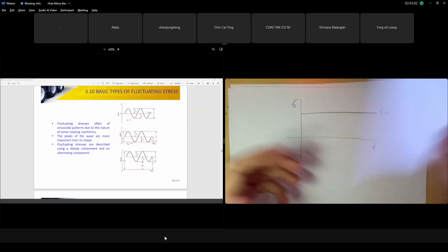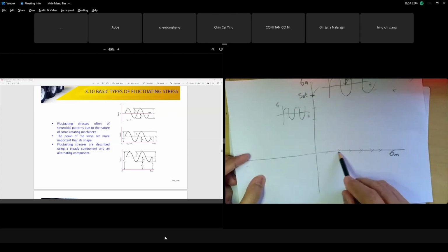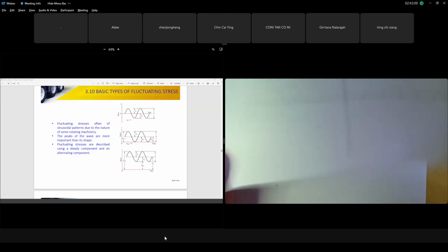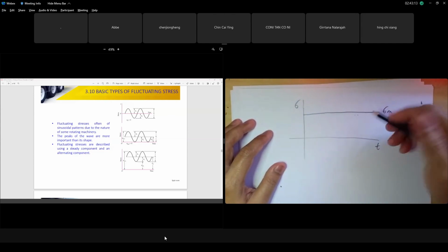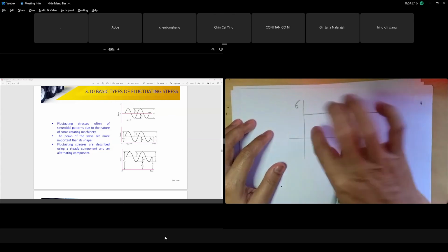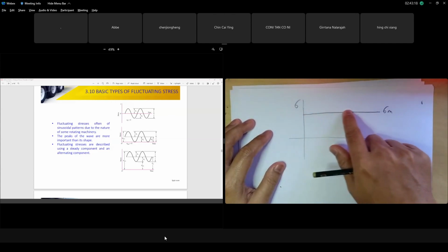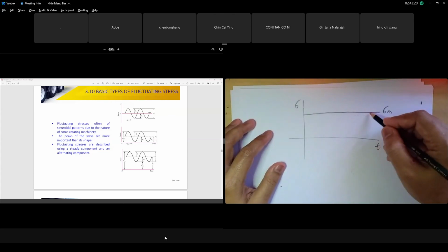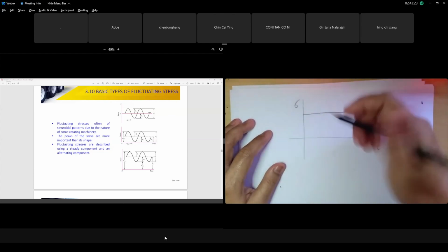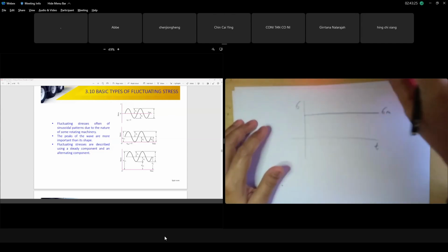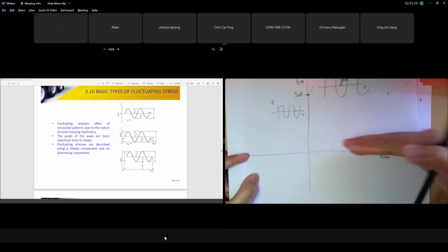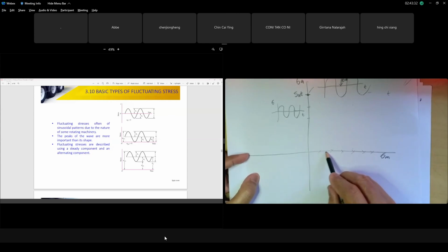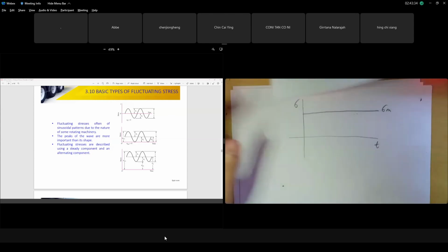Yeah, I just want to tell you that on this sigma m plot, all the points along the axis mean you don't have any amplitude. You have sigma mean through time, like constant loading, static loading. Your mean is the same. So your stress through time doesn't have sine waves like this. All along this line, where your sigma amplitude is 0, we have mean. So it means the stress is like this.